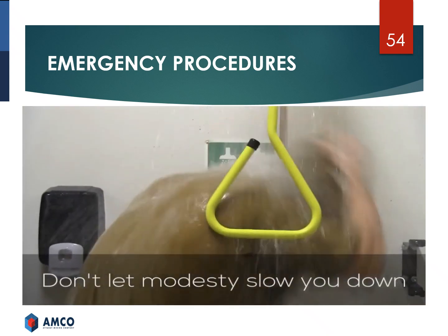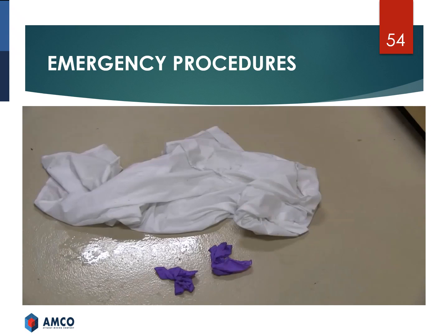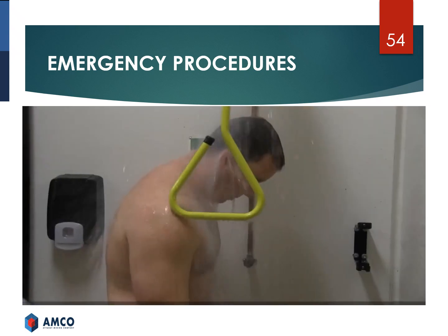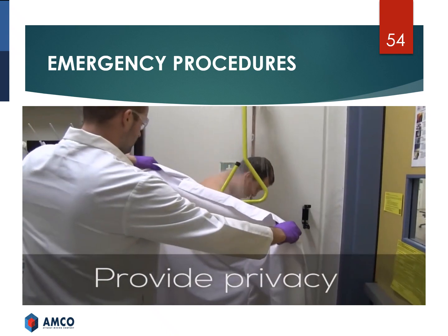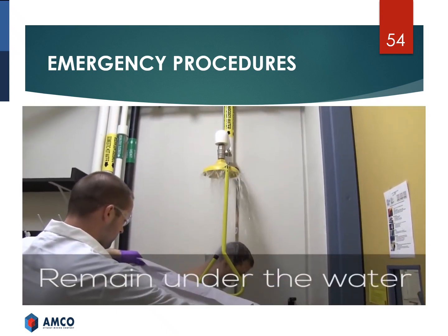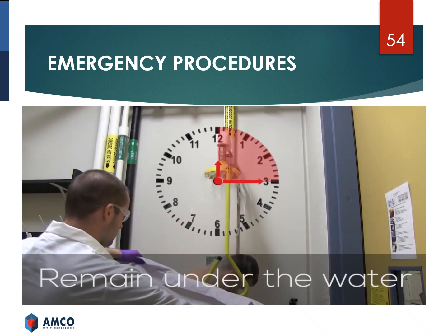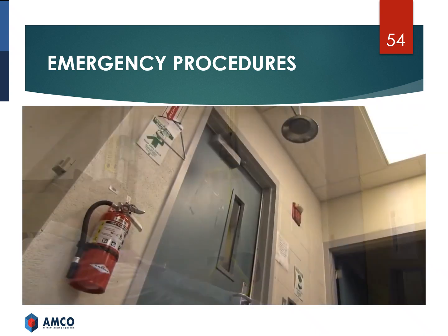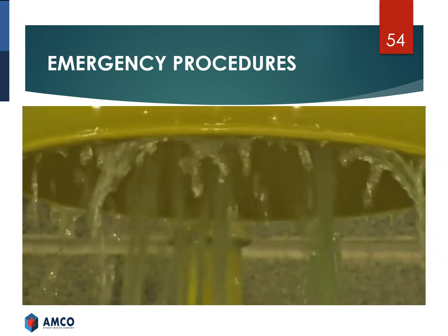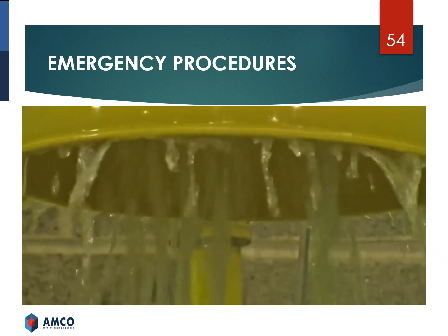Don't let modesty slow you down. Every second counts. Another person may provide privacy by shielding you with a lab coat or other item. Remain under the water for at least 15 minutes to allow time for the chemical to wash off. In addition to chemical exposure response, emergency showers can also be used effectively to extinguish clothing fires.